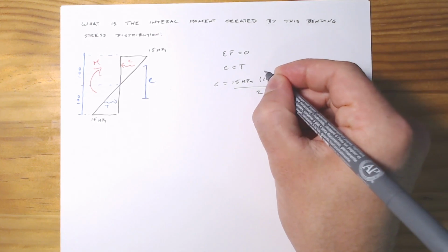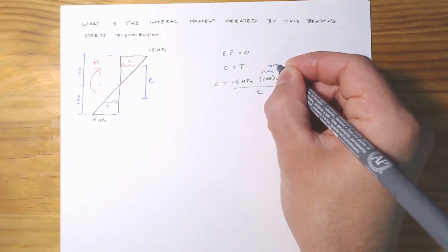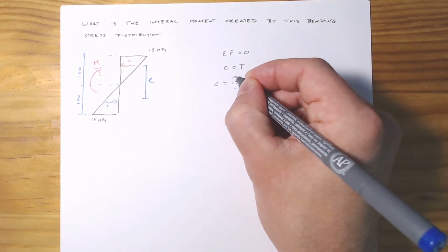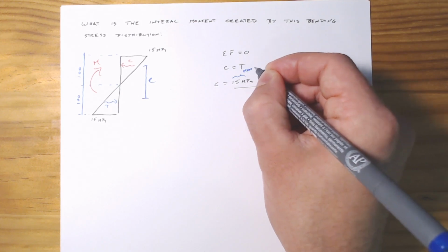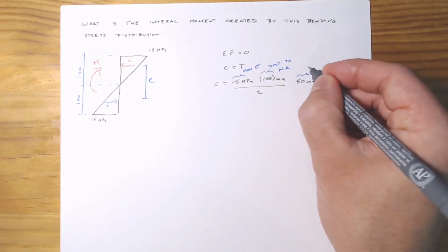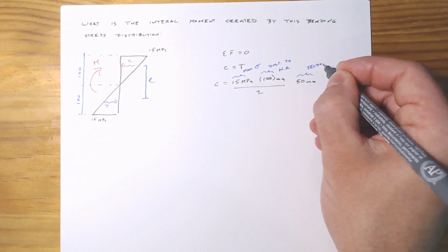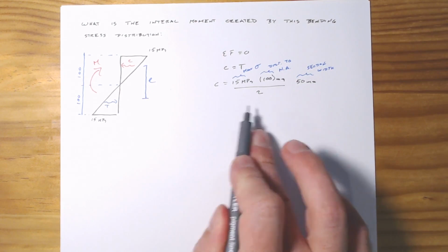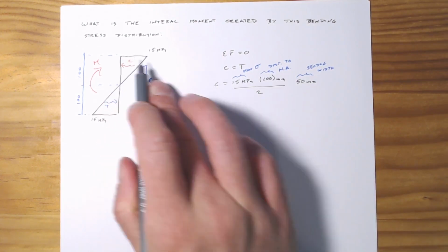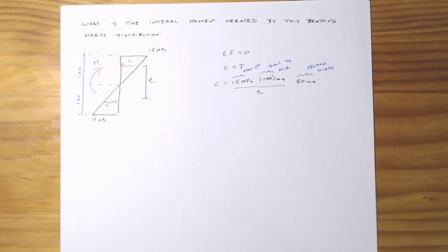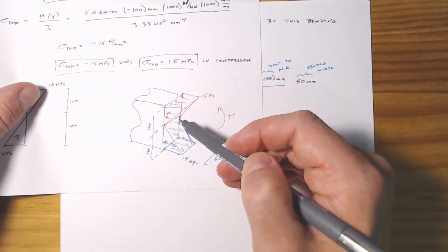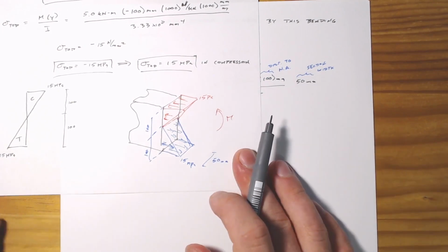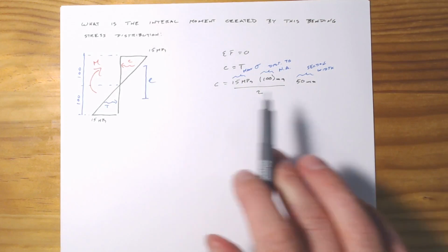This is the distance to the neutral axis. This is the max stress, and this is the section width. And so this portion here is effectively just the area, and then multiplied by the width going across. And again, hopefully you can see, you've got this area of the stress distribution. To get to a volume, we multiply by the section width. All right, so that's pretty straightforward.